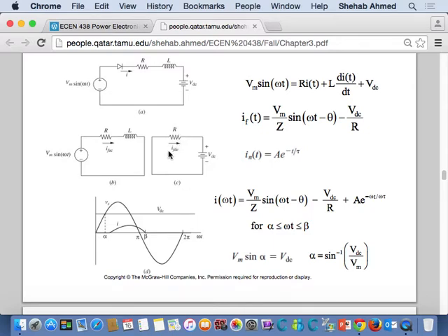because inductances are short circuits to DC, right? In DC circuits, in steady state, again, L di by dt does not exist. The di by dt does not exist. There's no change in current with respect to time. So you know that there's no voltage across the inductor. If the voltage across the inductor is zero, di by dt is zero, so the voltage across the inductor is zero. When something has a voltage of zero across it, that means it's a short circuit, right? So for DC circuits, inductors are short circuits. So you don't see it here.